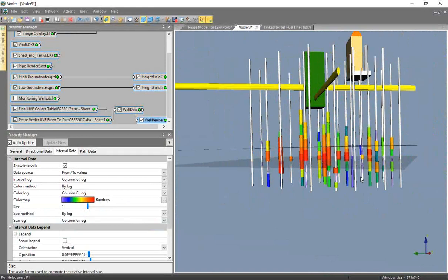So now that the borings and the water table levels have been added to the model and the 3D DXFs have been added, it's time to grid the data from the borings. So I've already extracted the data from these borings into an Excel file, which is going to be used as input to the gridder. So let me go ahead and load the point data into the project.